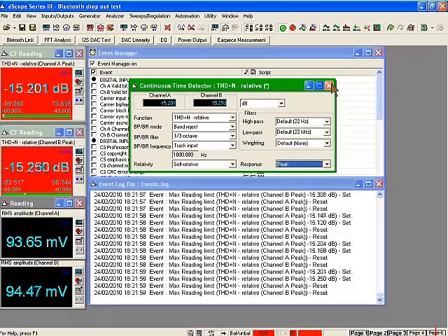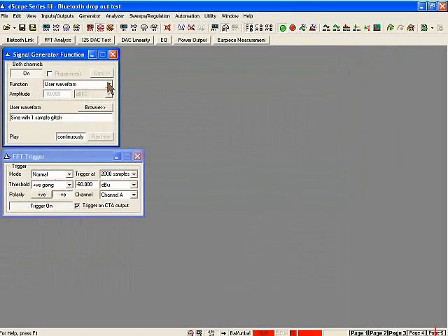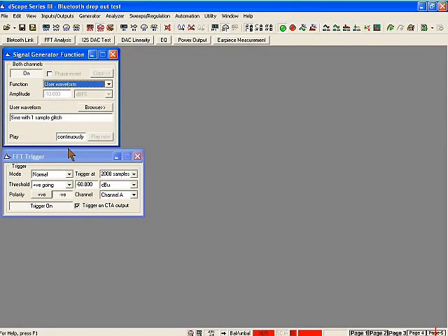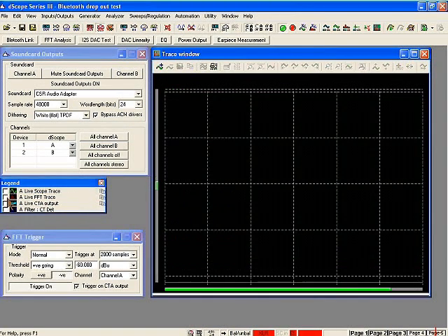I haven't really illustrated what's going on here, but what I have done is I've configured a special kind of waveform. I've loaded a user waveform, which can be anything. It's totally arbitrary, and I've loaded a wave file. This wave file I have configured deliberately to have one single sample of data in error. I've actually manually moved one sample of data in a digital audio editing package in order to produce a very, very small glitch. And if I now go to my time domain waveform here, what I'm going to do is add a couple of traces and then explain something to you.